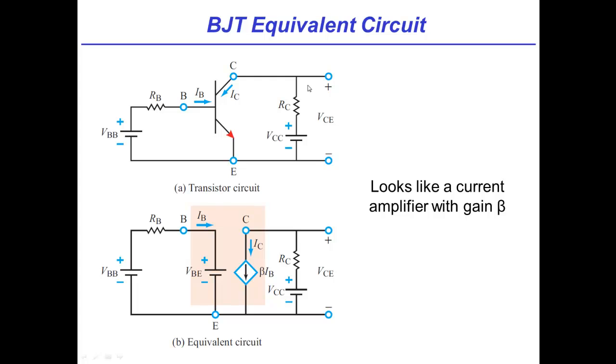Sounds good. So first of all, if I want to figure out what the transistor is doing at the output, I have to figure out the base current. Exactly. The base current's not that hard because I have one single little loop I can do KVL around. That's right. So VBB minus VBE is the voltage across this resistor. That voltage, VBB minus VBE divided by RB, by Ohm's law, gives me IB. Exactly. So IB is going to be set by the input source, its resistance, and then the little drop that the transistor forces on the input. So I can solve that.